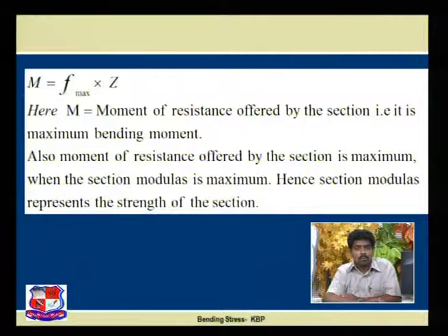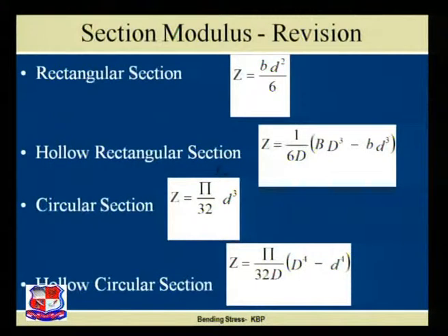It's the most important point, that section modulus represents the strength of section. If the section modulus is higher, the strength of section is high. If the section modulus is lower, the strength of section is less. Now the formulas for the section modulus.